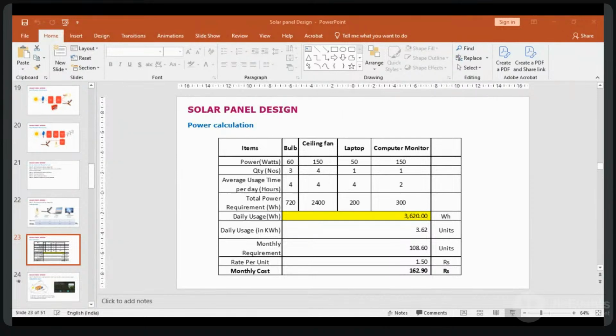Generally we mount the panel on an east to west path. The sun path, as already told, is not the same each and every day; a small degree of change will come. Generally while mounting, we take a constant of 12.7, like 13 degrees. But each day a small degree of change happens. In the drawing we have seen that in winter there is a dashed line; it will not coincide, it will move like summer. A small variation of degrees will be there. But as a thumb rule, this is how we mount the panel.